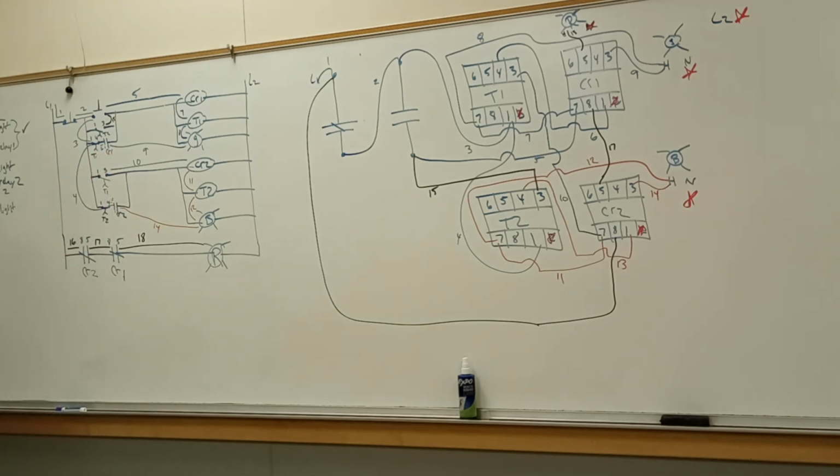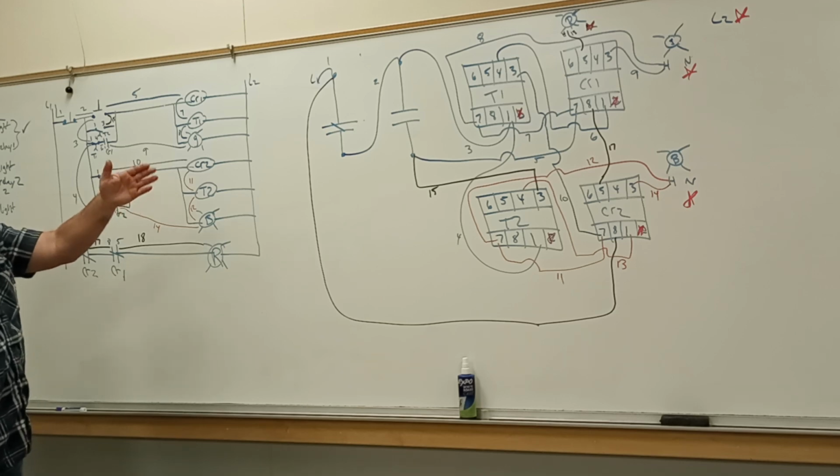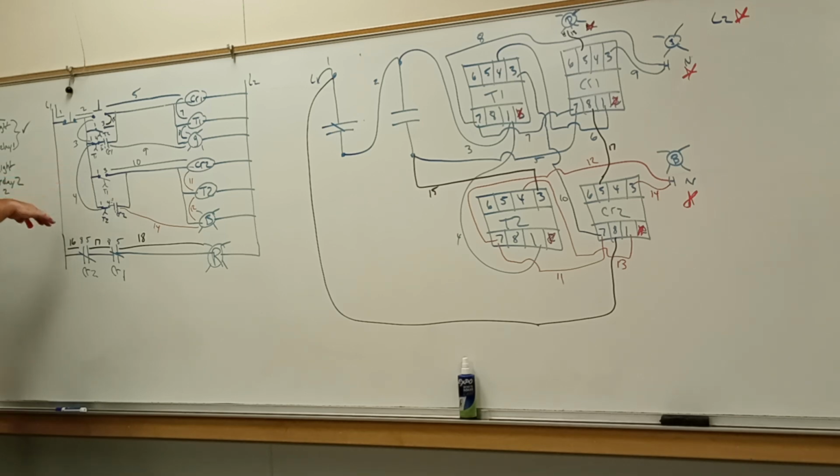Why would you use a second set? What can I do with the second set? Perhaps you're going to disable some other motor starter further down the line, or something else. Everything's going to be based on the same time because it's going to come on, so the contacts will shift at the same point, but you could further break it down a little bit easier so that if you wanted to wire it up, you wouldn't use 1 and 4, then you would also use this as 8 and 6 if you wanted to split it up.